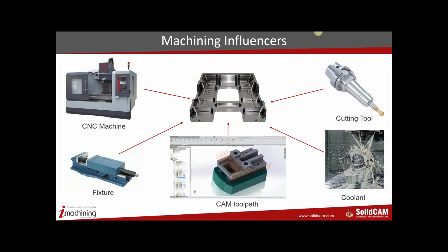The other important thing is how you're holding the tool. I've seen in many cases people taking a very expensive tool, they have a very expensive machine, they're cutting titanium, but they end up using collets instead of other regular holding mechanisms. Collets, by the way, have a very small holding area when you consider the length that's being held to clamp the particular tool. It's either just 1D or even less than 1D. So collets are a big no when you're cutting these materials.